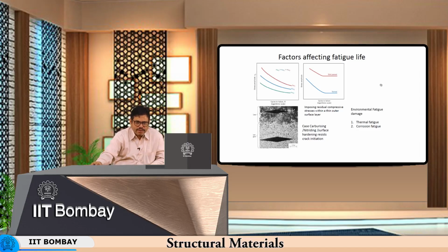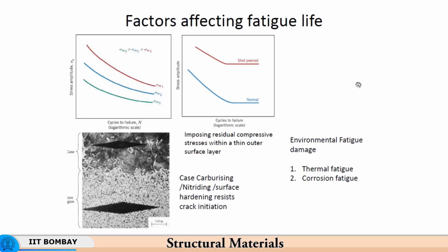So, if you look at it, the hardness is much higher on the surface. It is made out by the smaller indentation. So, loads are the same, but indentation is small on the hard surface as compared to the soft interior, where the indentation is much bigger.